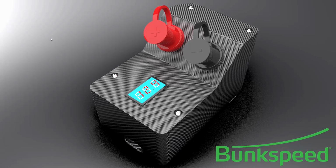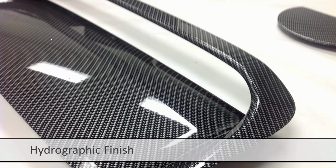So I think what I'm going to do is spend a little bit more time on the finishing and then have it hydro dipped. Hydro dipped is pretty cool. You would take a part that's finished, it's painted, in this case, say gloss black, very nice finish, and then you dip it onto a film that lays on water, and that film has a pattern on it, in this case like a carbon fiber pattern. The film clings to the part and conforms to its shape, and then you pull it out, you dry it, and then you clear coat it, and you end up with a part like this that looks like carbon fiber, but is not really carbon fiber. This is huge in automotive and the gun markets, so I might end up doing that, make it look a little bit better. All right, so that's about it.